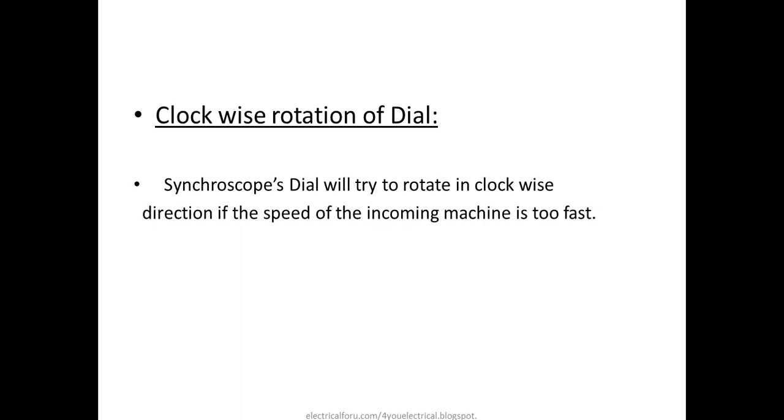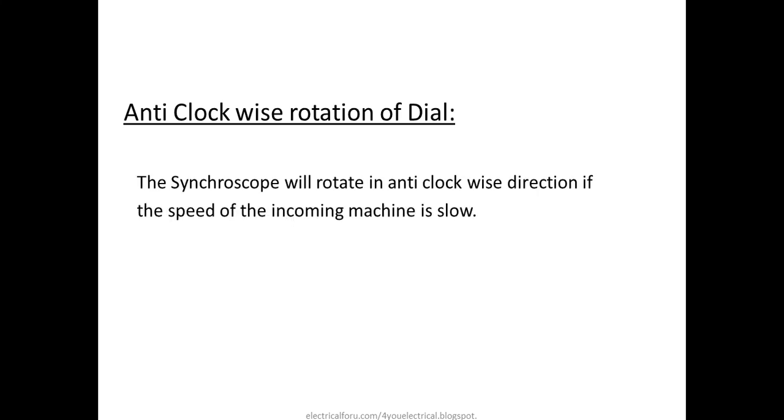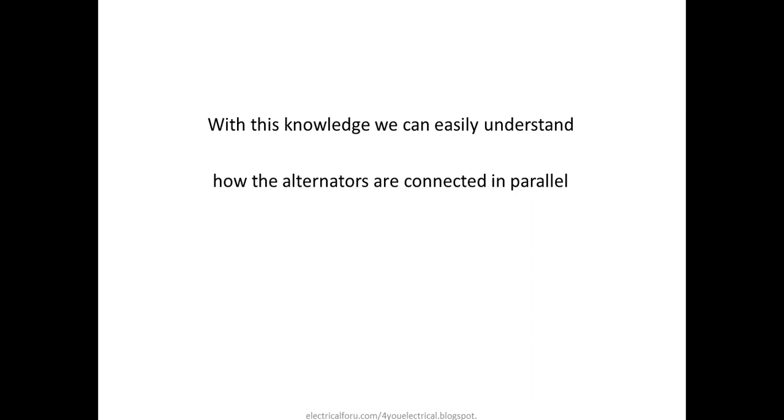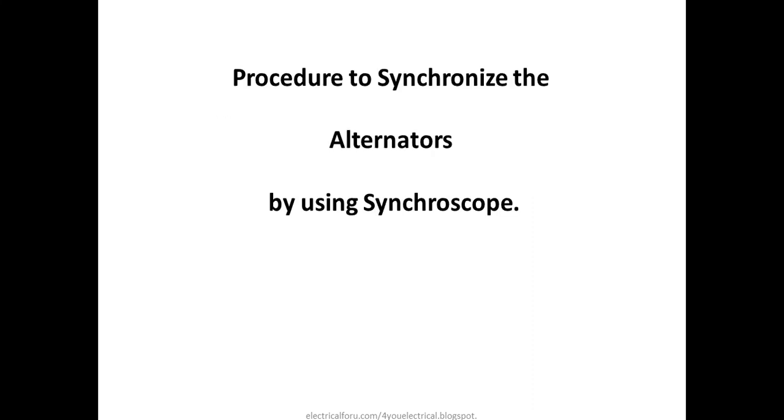When the dial rotates in the clockwise direction, the incoming machine is too fast. When the Synchroscope rotates in the anti-clockwise direction, the speed of the incoming machine is very slow. This is the process of the Synchroscope.